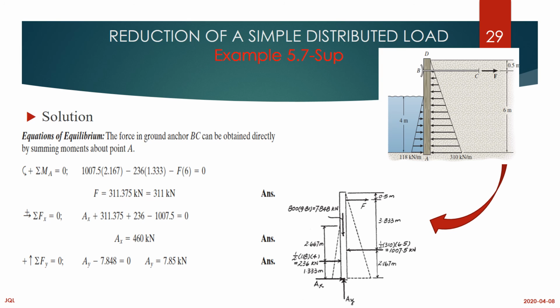As I was just explaining, you have a force there, you have another force there, you have another force here. I've got twisted. There's a pin here, right? Summation of moments about O, which happens to be this point, is supposed to be equal to 0. So we have got how many forces? 1, 2, 3, which happens to be the 107. How do you get the 107? By calculating half, the 310 times the 6.5.